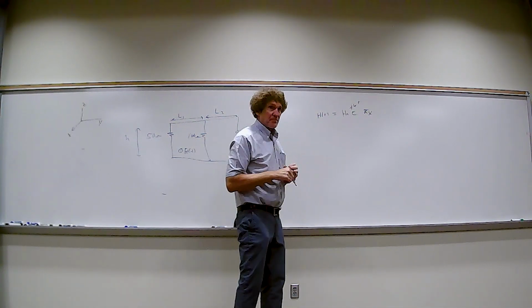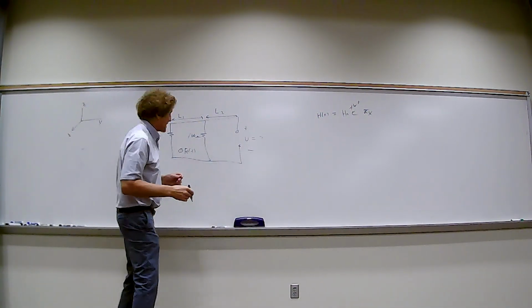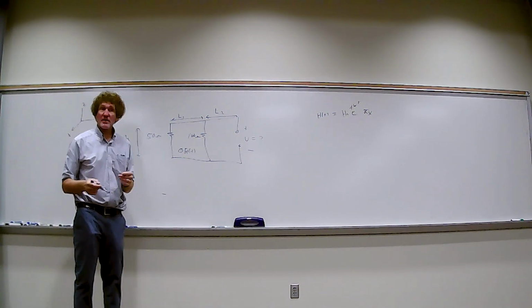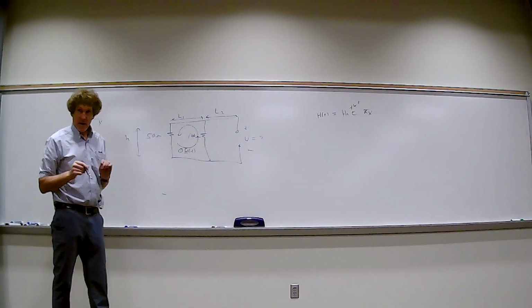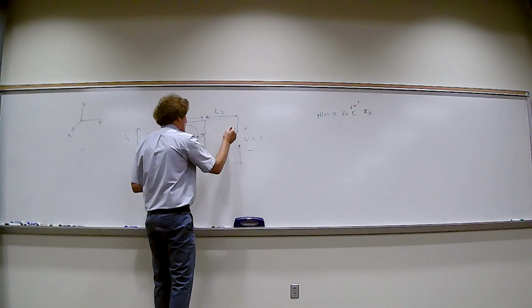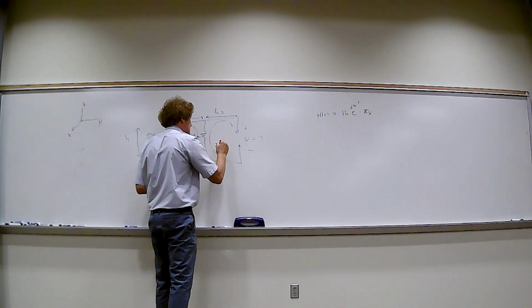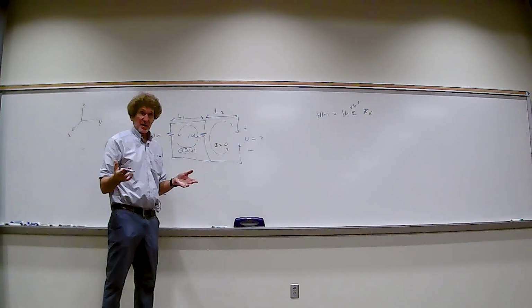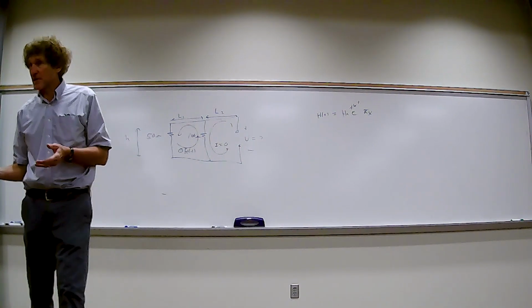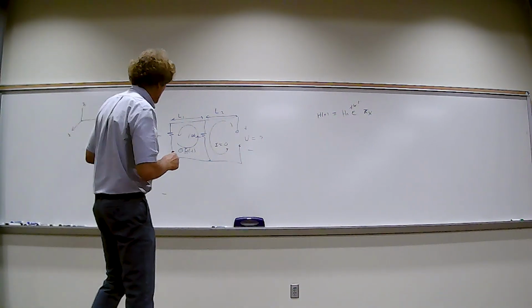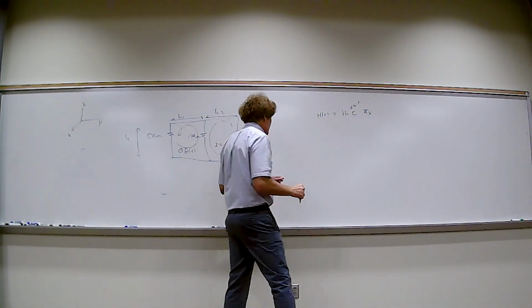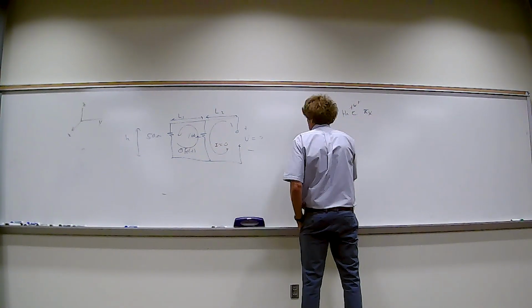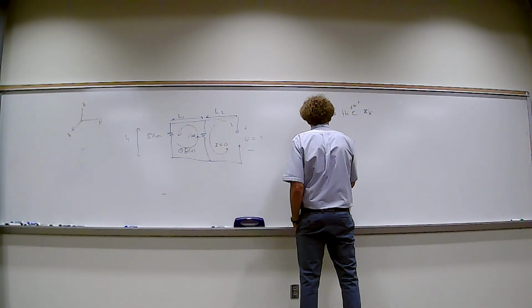Now, if you look at this problem, and I want this voltage, you have to see where closed paths are and where paths are not closed. You all see that there's a loop here that's got a closed path. Current can flow in that loop. You all agree with that? No current's going to flow here. I will be zero flowing here. If you think about mesh analysis, y'all with me? No current's going to flow in that second loop, but there is going to be a source. So what typically you do is this. Draw the dimensions up. And I'm just going to do this.